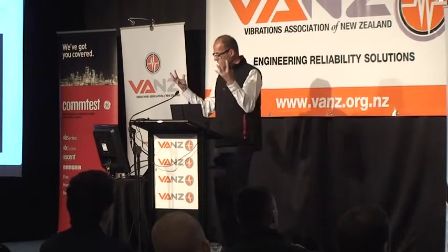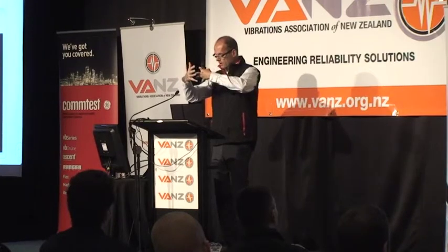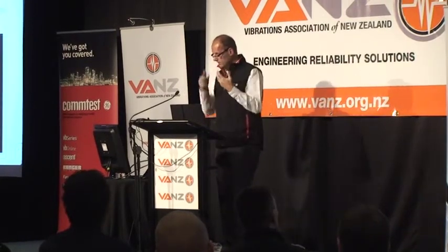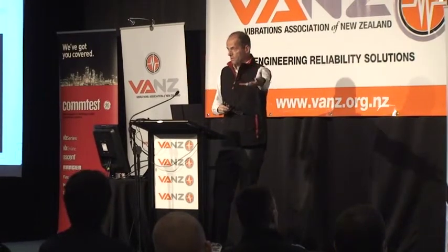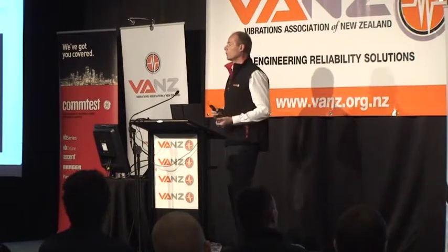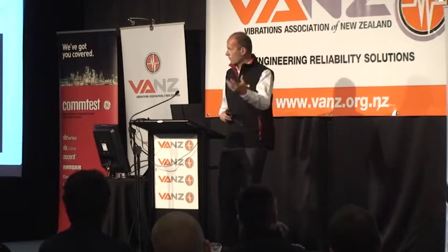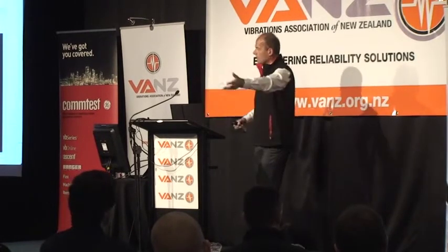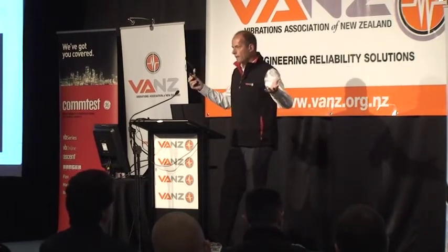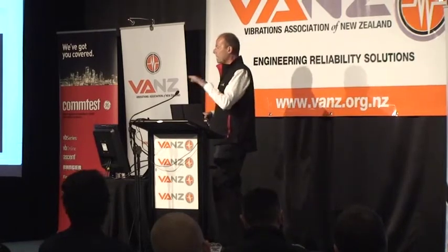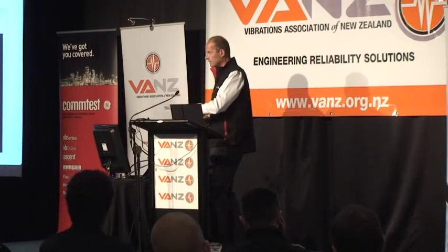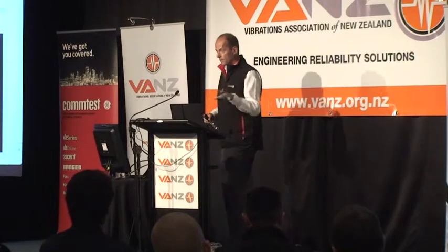And the more technologies we use, the more we get a complete picture. If you're trying to make a critical decision about what to do with a piece of equipment, does it have a problem or not? Am I going to request that the bearings are replaced but there's nothing wrong with the bearings, or that it should be aligned or balanced? The most common reason a balance job does not succeed is because the machine was never out of balance in the first place.